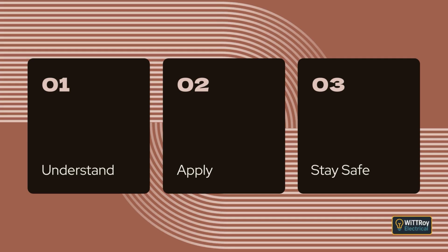These include when they are used as aerial conductors, when they are inside a wall cavity very close to an accessory or wiring enclosure, when they are inside a switchboard or similar enclosure where they cannot be touched during normal operation, when they are earth or bonding conductors installed under Section 5, or when they are extra low voltage conductors under Section 7.5. Clause 3.10.1.2 Insulated and sheathed cables.